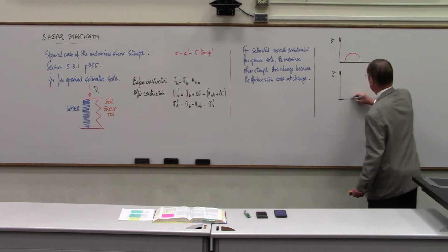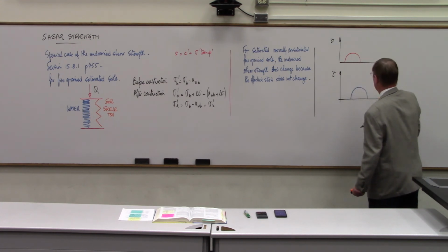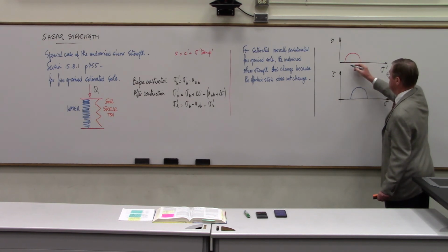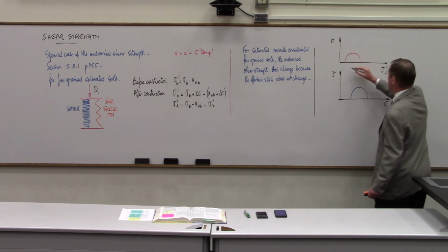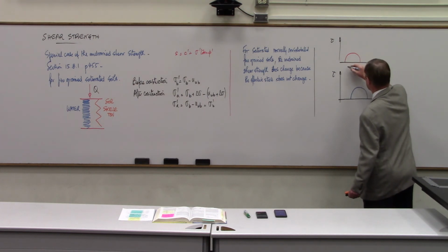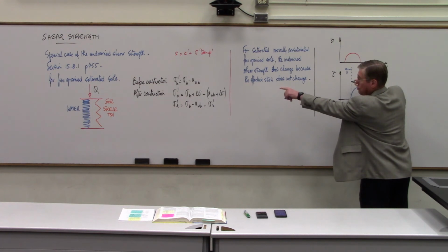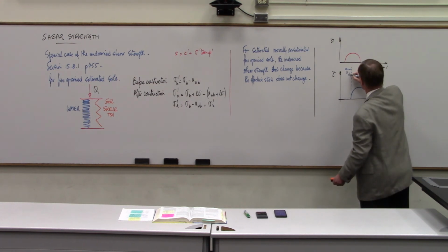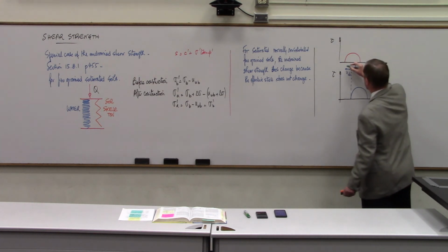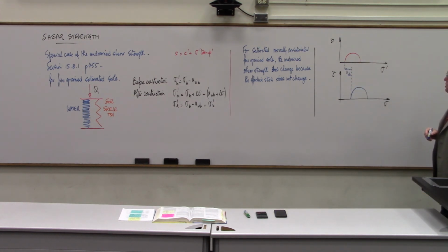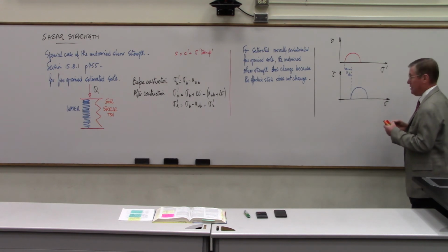All right, that Mohr circle will come out here. Why? Because the total stress is equal to the effective stress plus the pore water pressure. So this is going to be sigma prime 3, so when I go up this way, I have to subtract the pore water pressure, u_wB, and that gets me to this stress right here.